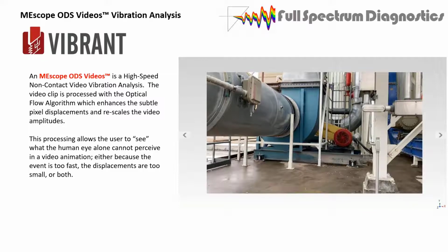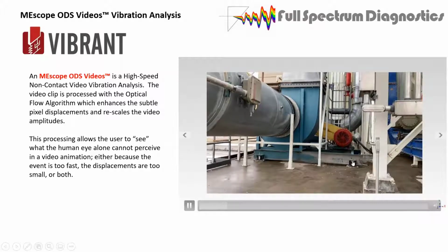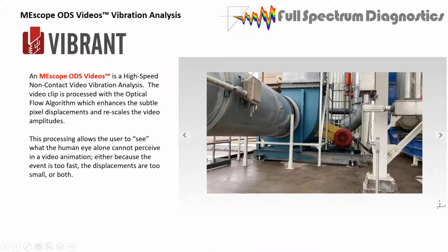And we found that it was so flexible that it would be a better idea to put isolators under it. And we'll talk about this a little bit more in a minute or two, but you can see the two isolators out front. They changed two of them and they left two of them bottomed out. So it wasn't very helpful. So this is where we came in and took a video. It seems like it's backwards, but we took a video to see how our change was manifesting itself, and we had to go back in and add those other two isolators that were kind of bottomed out.